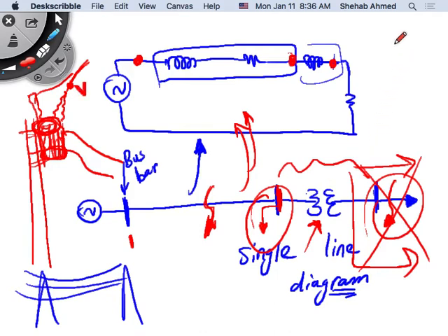So you have these insulators that have bodies, for example, that look like this, where the high voltage terminal is coming in here, and then it's going into the transformer. The transformer chassis or body will typically be grounded or connected to the neutral wire. We'll talk more about that: when do you connect to neutral only, when do you connect to ground. We will have a nice section discussing that as well at some point.